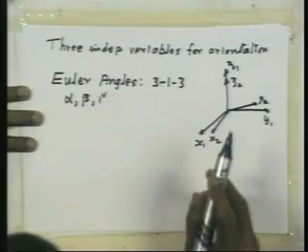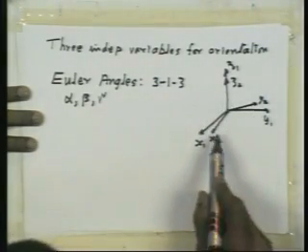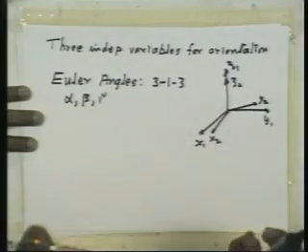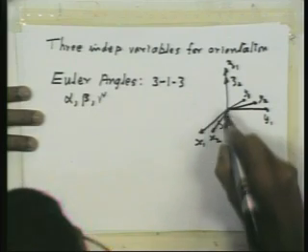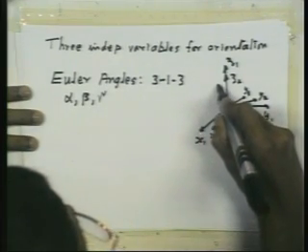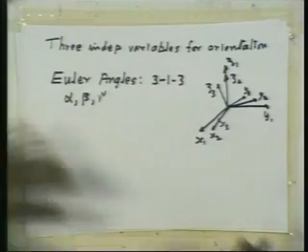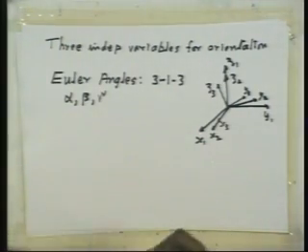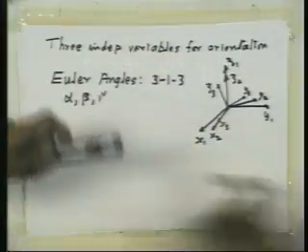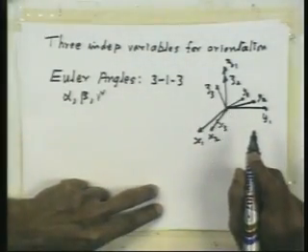So next what you do is, the local frame is now at x2, y2, z2. Now rotate the local frame about the x2 axis. Fine. If you do that, the new position x3 will be here itself, y2 would go to y3 like this, z2 will go to z3 like this. Fine. And finally a rotation about z3, right?